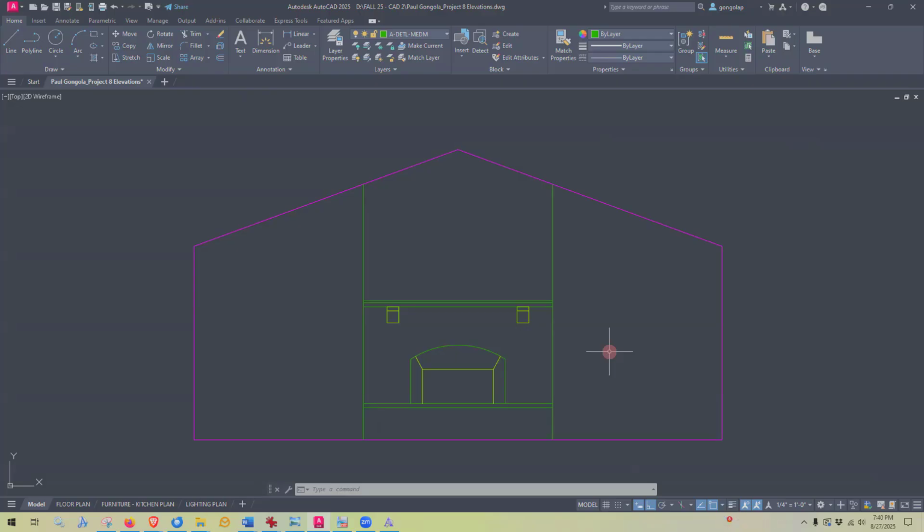You can do a lot of work in 10 minutes, but there is a lovely command called save time. And if you were in my CAD class, you already know about it. If you type save time, it asks for a new value for save time. And sure enough, mine is set to 10, as in 10 minutes.